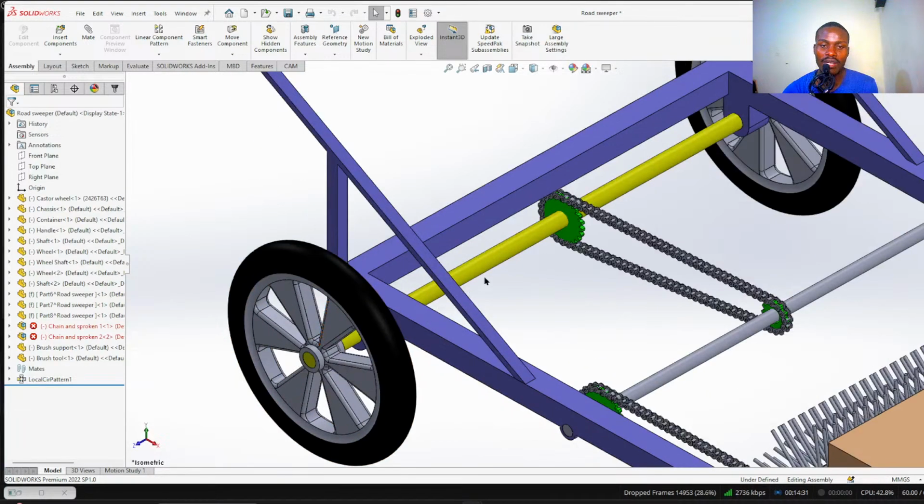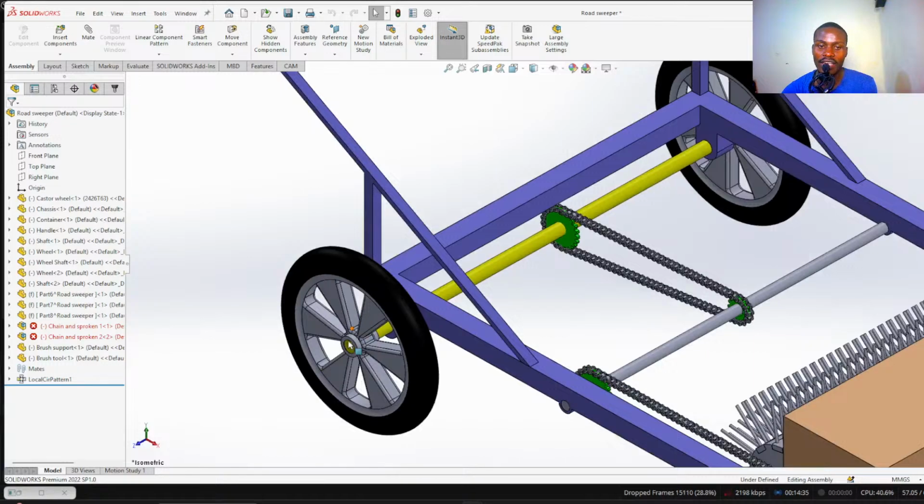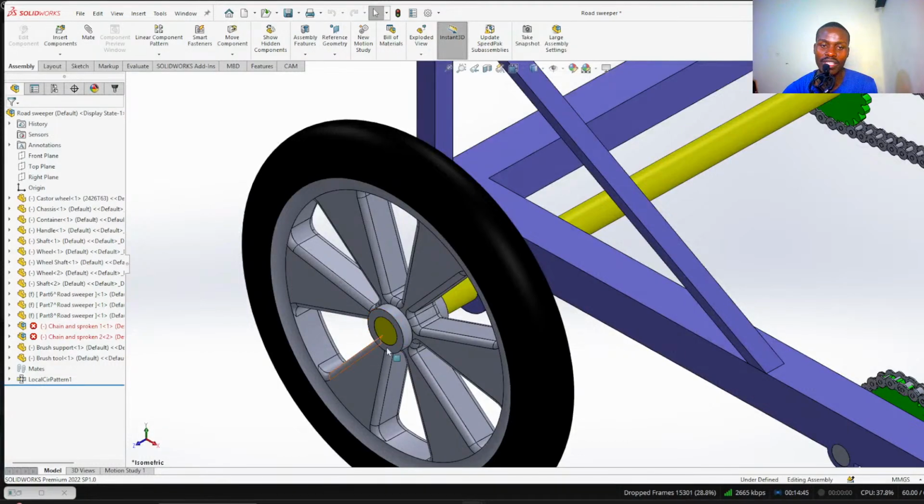And then when you come to shafts, you cannot use a continuous solid shaft. It has to be hollow along the middle part, and then towards the end where you connect the tire, you can use a solid shaft, and then you can weld it. And of course, use a key to join.